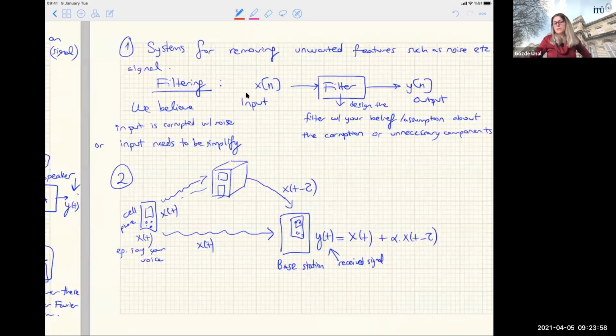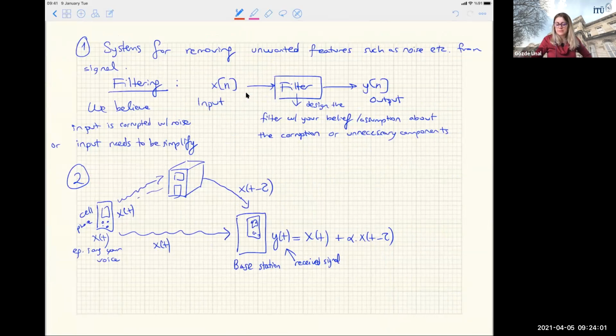A model means, first, if it's a smoothing or averaging filter, that's a model. If it's a high pass filter, that's a model. A parameter is, for instance, if it's an averaging filter, how many signal coefficients I am averaging in one shot. So here, for instance, this is a part of the model, a parameter of the model. We will see it helps in modeling the decay.